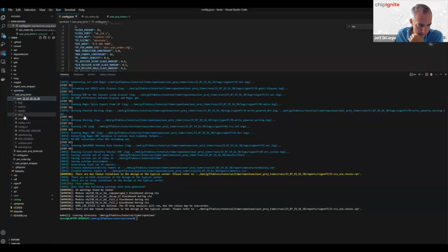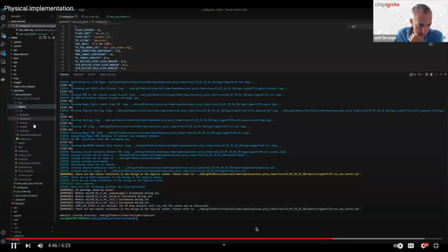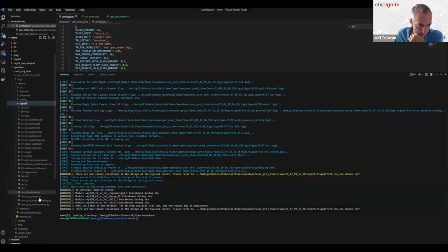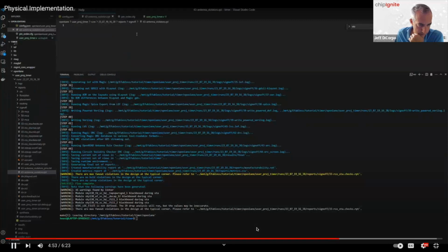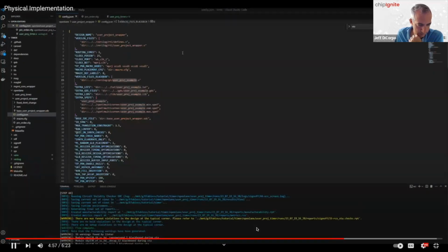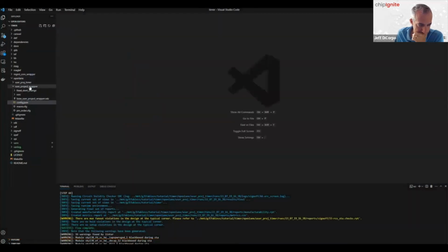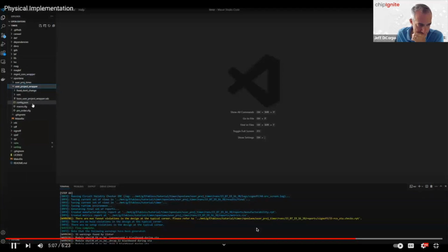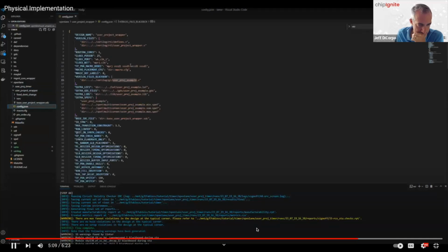We can check the antenna violations in OpenLane runs, last run folder, reports, signoff, 43-antenna_violators.report. But there are none, so that's great. Now we can harden the user project wrapper, which will have our macro, and this is what will be integrated into Caravel. So let's go to the OpenLane folder, user_project_wrapper. First, we will edit the config.json file.